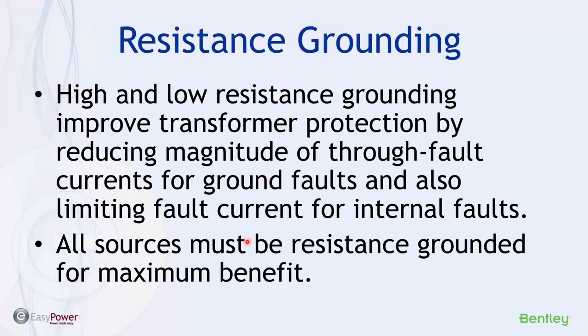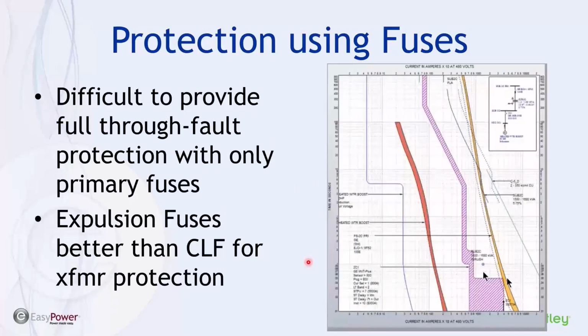But again, to remove the potential for grounding to be a problem, you should have all your sources in the same mode of limiting maximum ground current.